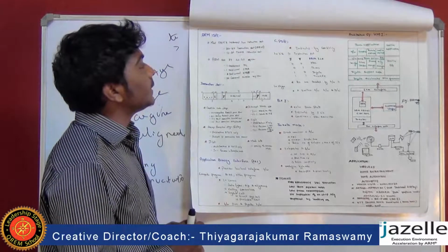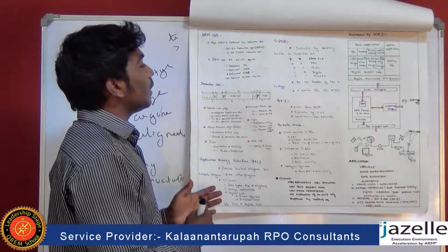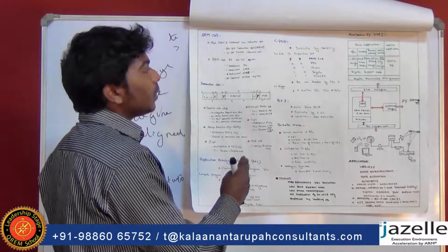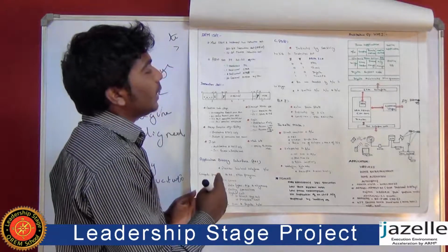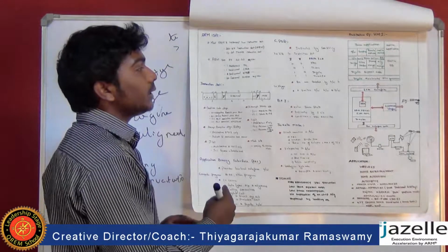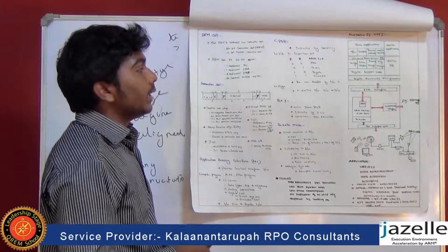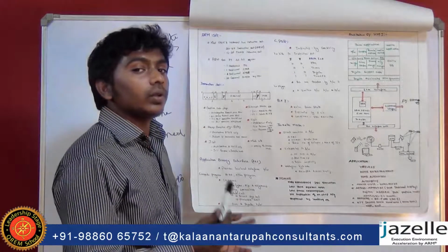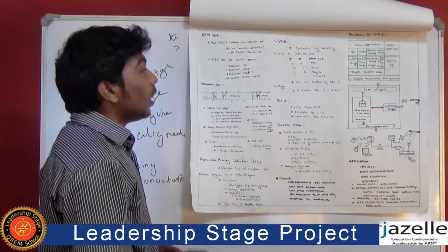And the next one is CPSR, that is current program status register. As I mentioned already, it is used for maintaining the current status of the processor. It is indicated by two bits, that is T-bit and J-bit. If the J-bit and T-bit are 0, the instruction is in ARM state, and if J-bit is set to 0 and the T-bit is 1, then it is in Thumb state. And if the J-bit is 1 and the T-bit is 0, it is in Jazelle mode. If both bits are set to 1, then it is in ThumbEE mode.